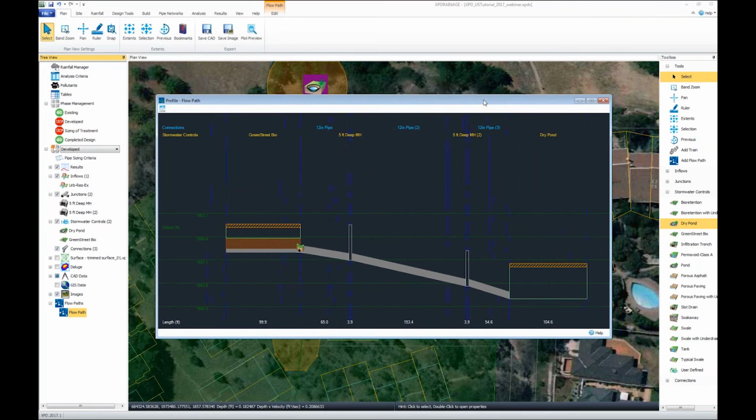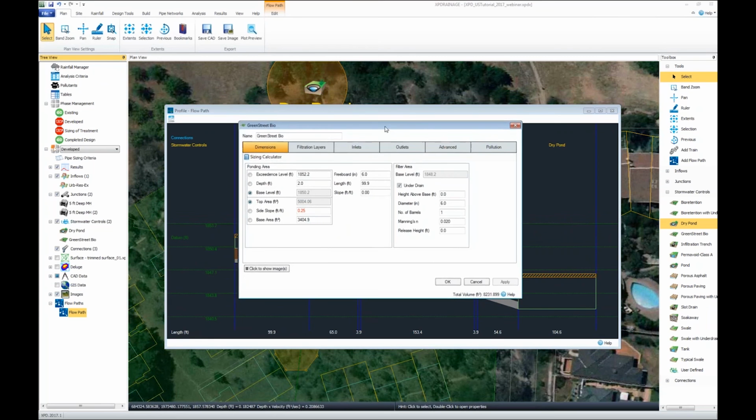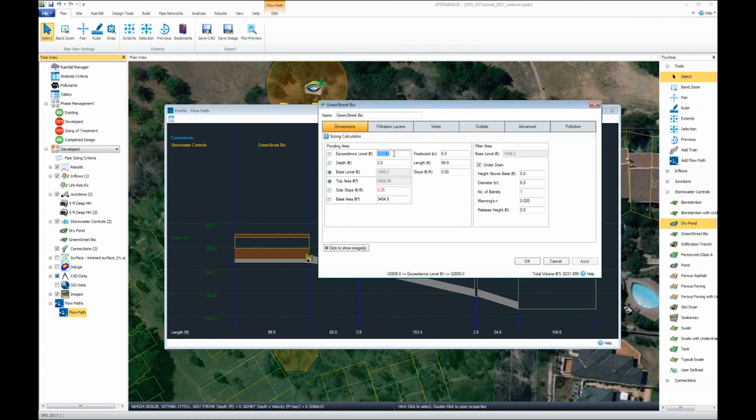Now, we're starting with the existing elevation, so this probably won't be the exact final grade. These might be adjusted. So we can adjust that by bringing in a new surface. We can manually adjust these values. You can see I can directly edit from a profile. Maybe I'll manually edit the top elevation of a facility. That's what the red text is, something I manually changed. We'll see how it updates the profile.